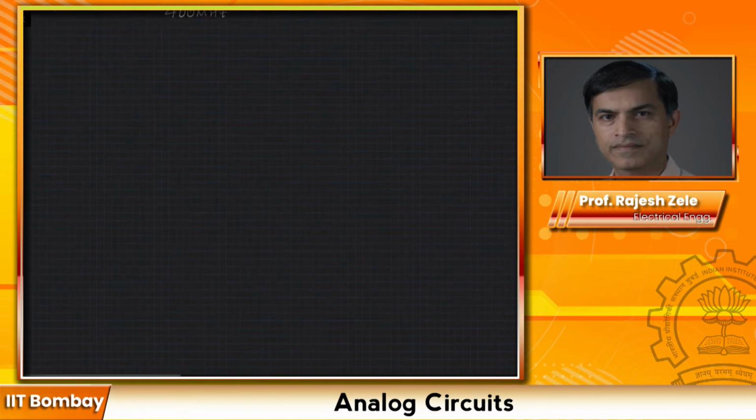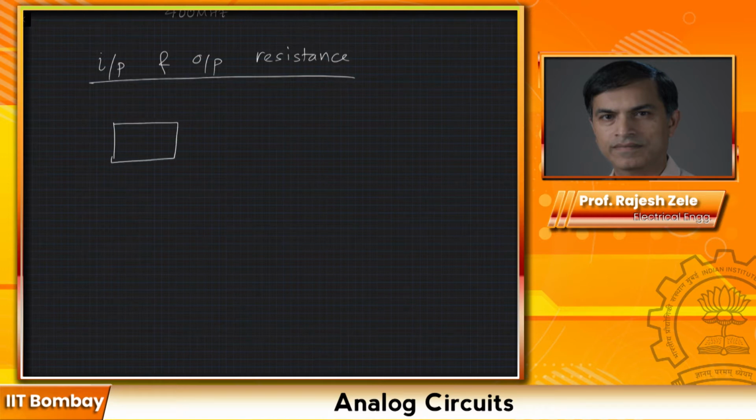Now we will move on to the next property or definition, which is input and output resistance. For that, let's say there is this box, and this is the ground. There is input and output. When we want to measure input resistance, we generally apply a test voltage source at the input, and then we measure how much current is going in, I test. And then we say that Rin is equal to V test divided by I test.